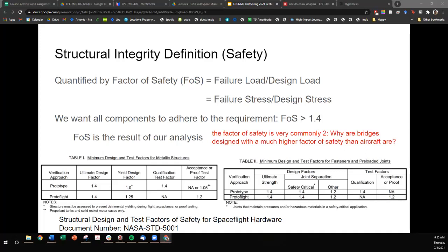The field of aerospace engineering uses generally lower design factors because the costs associated with structural weight are high. For example, an aircraft with an overall safety factor of 5 would probably be too heavy to get off the ground. Remember that factor of safety can be cranked up by adding more mass to a system. So that's why we keep it low.